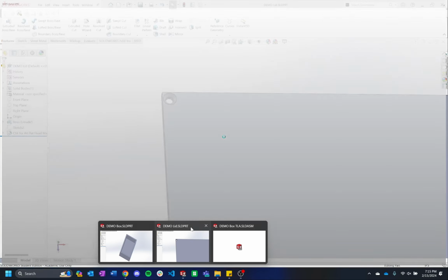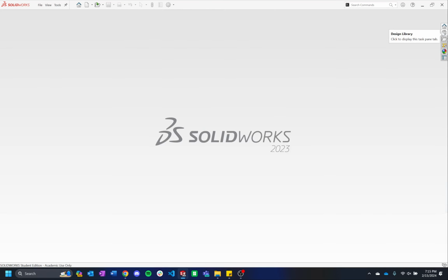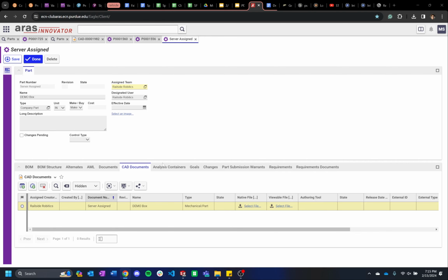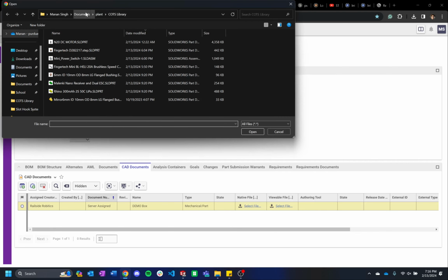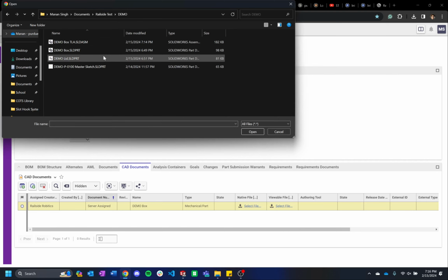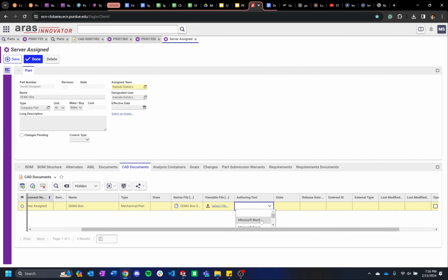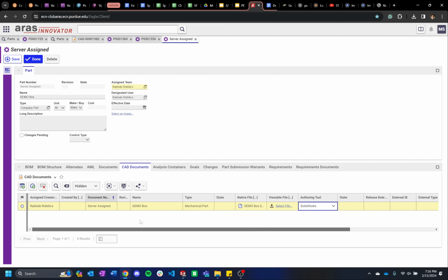I'm going to have to close all this on SOLIDWORKS before I can upload it. I don't know if it's going to give you an error if you try uploading it while it's open in SOLIDWORKS, or if it's just going to corrupt. I think I did it and it worked. I know that SOLIDWORKS puts locks on its files, so back when my FRC team would use GrabCAD for PDM, if you tried uploading a file, it would be corrupted. So I would always just close it. And if you have an assembly, it's still open, so you need to close the assembly as well.